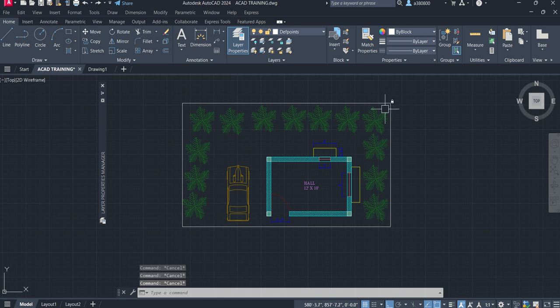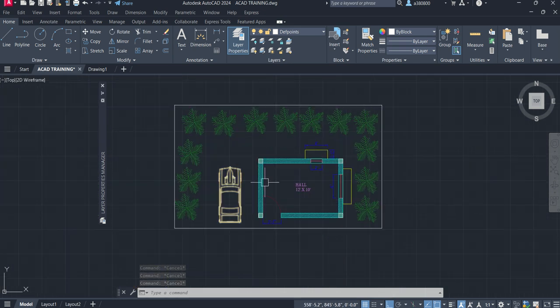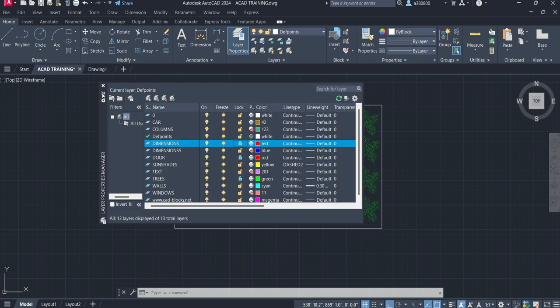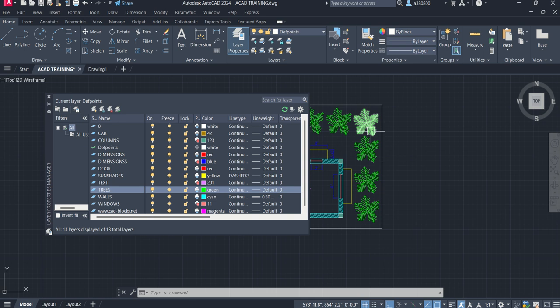By mistake in some of the parts, we delete things unwantedly. So to save that, you can just lock the layers, or later on you can unlock the layers, right? It's entirely up to you. You cannot change anything for the layer which is locked by you, right?